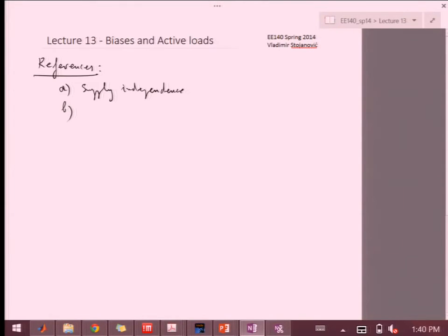So whenever you design chips, you will always test functionality over process variations, supply, and temperature. And those are not just environmental conditions, but it's also heat cycles that the chip is going through. And things are very active, very hot. You're getting junction temperatures around 100, 120 degrees C. And then you can get them cooled down to -40 in some extreme environments. So over that whole range, things have to work.